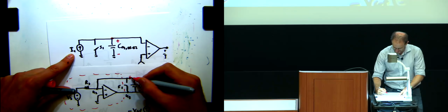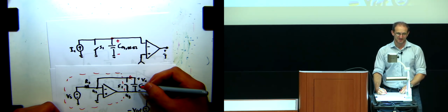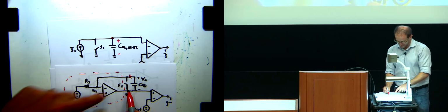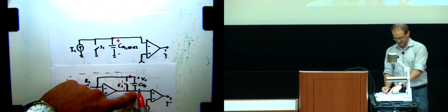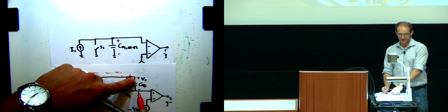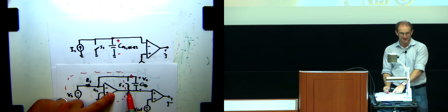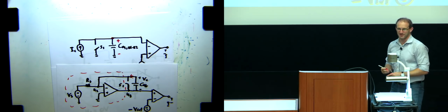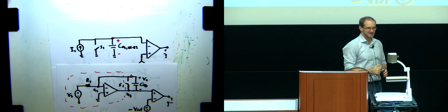If it's flowing in that direction, the plus should be here and the minus should be there, once again by passive sign convention. But now notice U3 relative to ground, U2 is also ground, but the minus side is here and the plus side is there. So just by looking at it, because the signs are flipped, U3 is equal to minus this VC. Make sense? It's a good question. More questions on this?